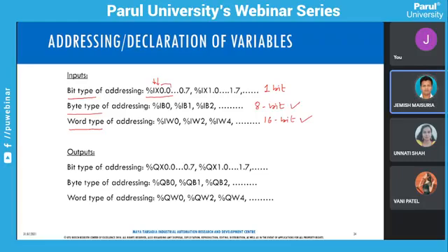If different kinds of ports are there, then in that, this is port 0 and pin 0. Same way, this is input, and then after this, B for byte, and the whole port will be used. So port 0, port 1, something like that. And this is for the word. And the same way for the output, but for output we use the character Q. So this way you can provide the name or address to those variables.